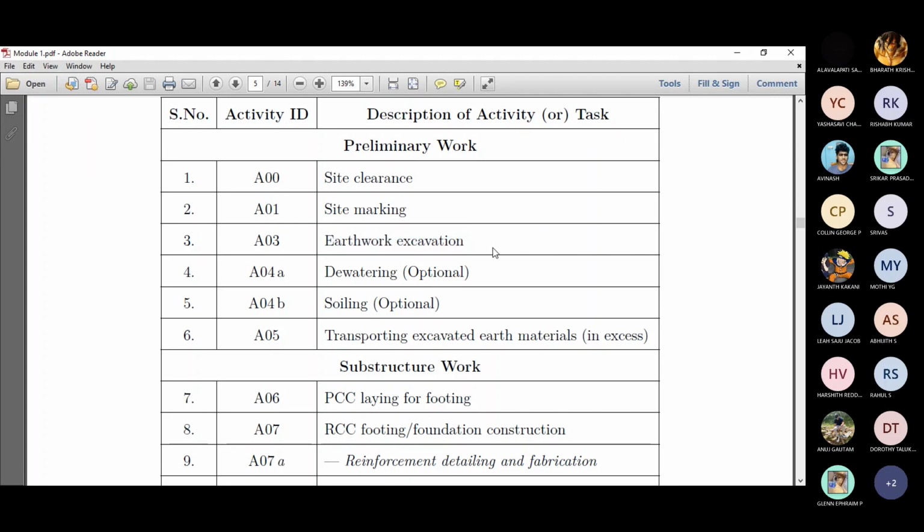But generally for this example, we take it that we don't have any space constraint, so we'll look into the isolated footing, and that particular quantity gets excavated, with the definite width, breadth, and depth for it. So it could be a shallow foundation, right? We don't really look into pile foundation for this. Say single story, say the hard stratum is really good, and then we go for the shallow foundation, specifically the RCC isolated footing, right? And then we talk about dewatering.